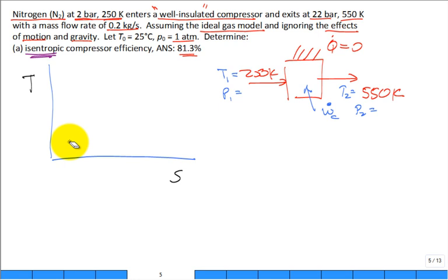Okay. So, this is one of those hard things. On a temperature entropy diagram, if you had a process that started maybe state 1 here, and they said, oh, it's a constant temperature process, it would either go like this or like that. All right. Let's do this. Start the process here. If it was a constant entropy process, it could go like this or like that. So those we have down pretty easy. But, oh boy, we have to recall for an ideal gas, what does a line of constant pressure look like? What does it look like if I had a constant pressure process, and right there is a line of constant pressure? That line of constant pressure is the 2-bar line.